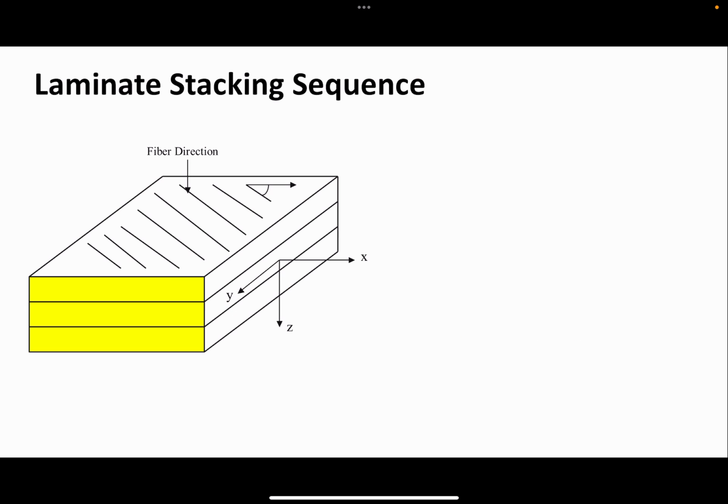That's the meaning. Here, because they are also made of different materials, you have to mention that graphite, Gr, 0 are graphite, plus and minus 45 are boron. So this is how you write laminate codes or the stacking sequence. So there are special types of laminates. Symmetric we just saw. Balanced laminate.